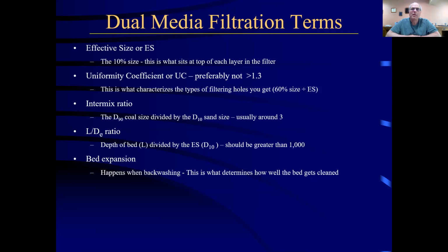But when you backwash the bed, basically what you're doing is expanding it by lifting some of those particles up, or all those particles up, by the water rushing back upwards against it. If you expand the bed too much, the bed won't clean itself. If you don't expand it enough, it won't clean itself. There's got to be a goal that you need to reach, and that's the bed expansion percentage that you should figure out for yourselves.